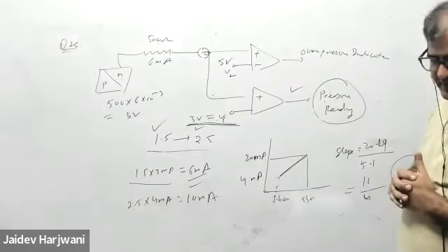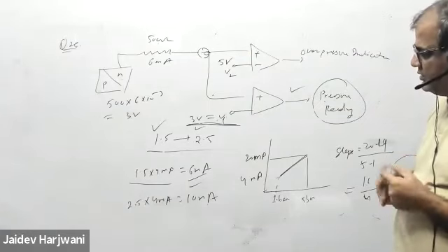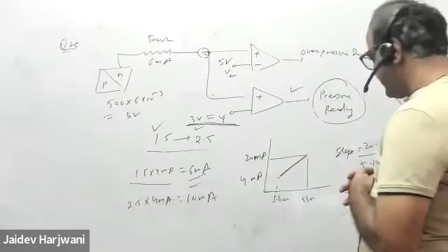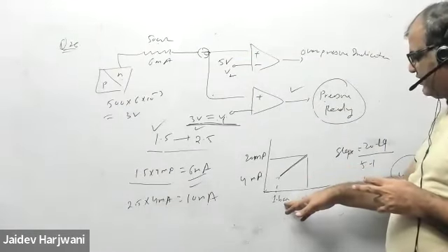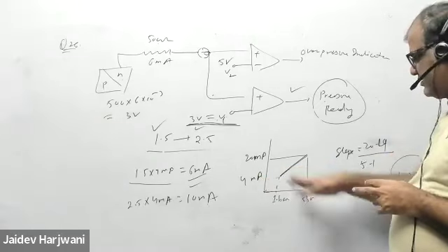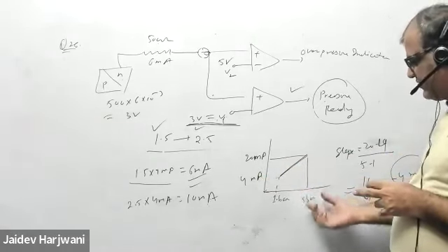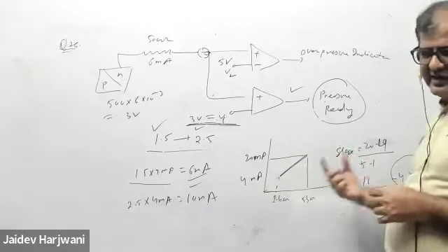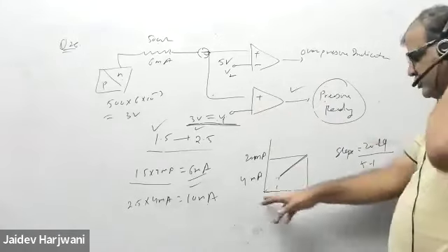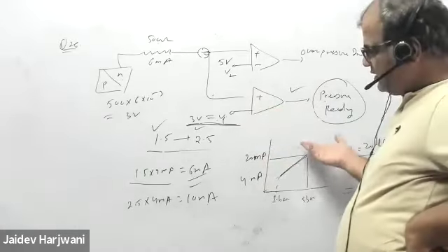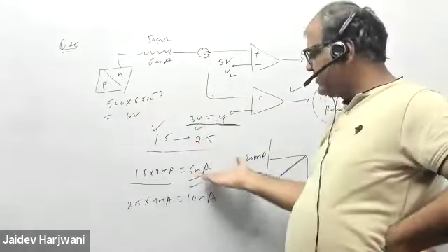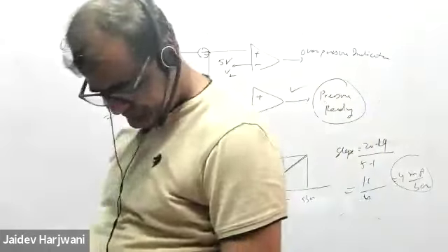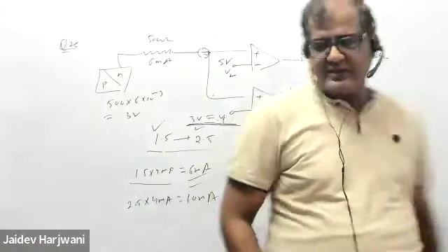Not about producing. We draw a graph between 1 to 5 using the range. See, they already gave some values, na? For 1 it will be 4, and for 5 it will be 20. So I know by slope. Now for any bar, I can calculate approximately how much current will be there. For 0 bar, there will be 0 current. So for 1.5 bar, how much current will be there? We calculate, and then fix these voltages. We calculate the voltage by IR, right? Yes.